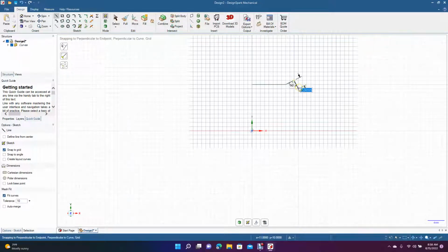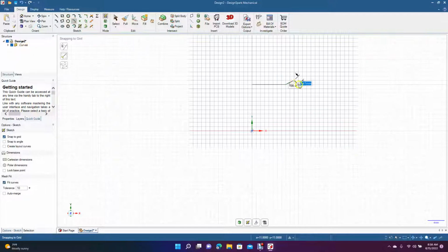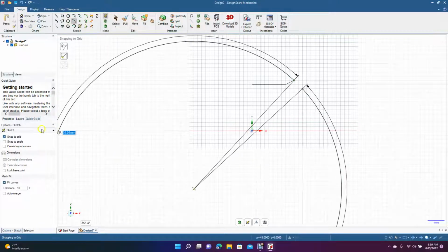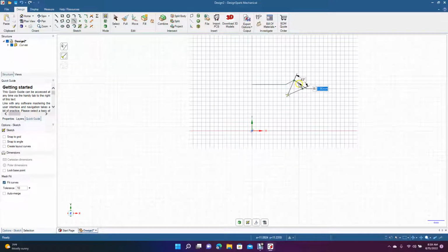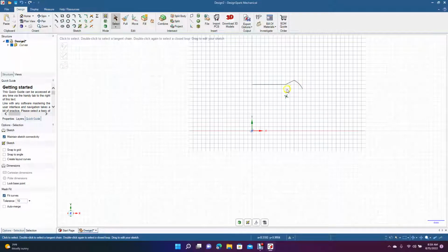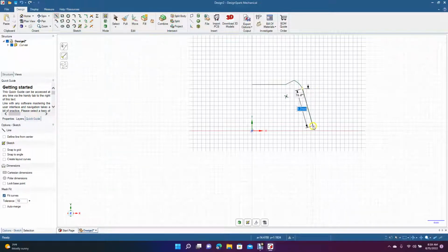It kind of comes like, actually, let's select the click off. Let's put a 3-point arch in there. We're going to curve this. Turn off the snaps. Come over there and click. I just want this to be kind of subtle right there. Okay, so this is the top part of it, and then inside of here is where the speaker goes. So we're going to get our line tool. Now we're going to create this shape down here like this.